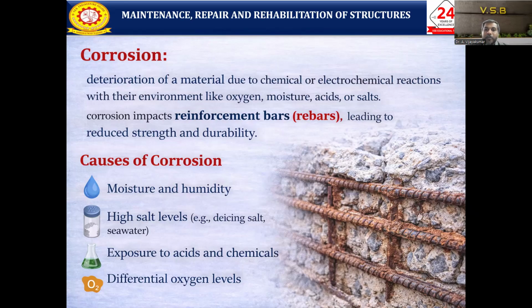Once corrosion starts, what will happen? It reduces strength and durability. So these are the various causes of corrosion. Moisture and humidity are one of the reasons. High salt levels, for example de-icing salt and seawater, may also lead to corrosion of the reinforcement.